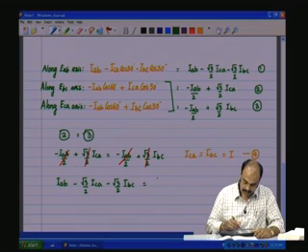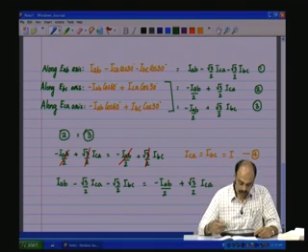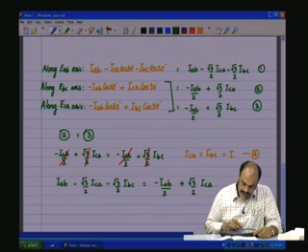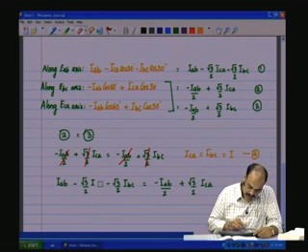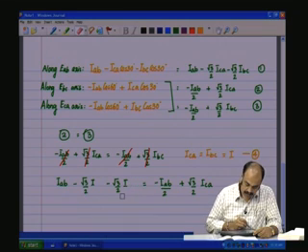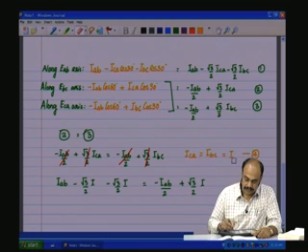Let us say it is equal to the second, minus IAB by 2 plus root 3 by 2 ICA. We know that ICA equals IBC equals I, so we make that change: ICA and IBC are equal to the same value I. So, we have substituted I in the equation.